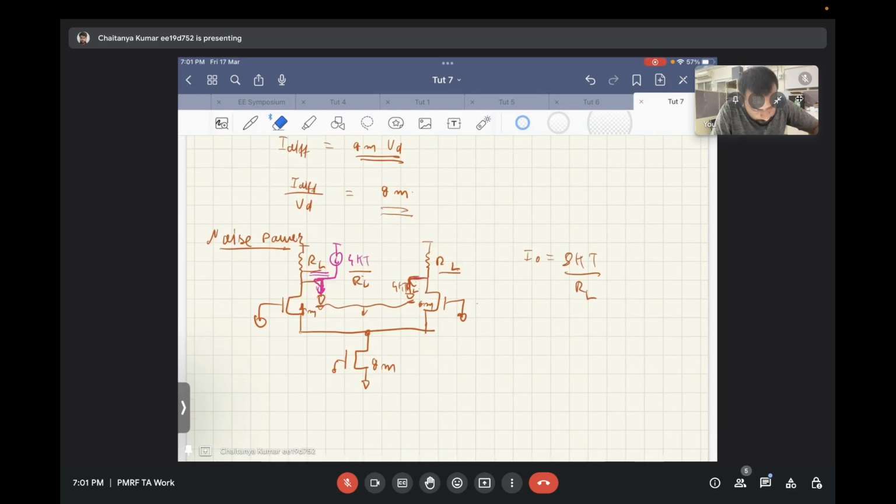Sir, sorry for interrupting, you're telling me about unbalanced output, right, sir? That's not the reason. The noise is uncorrelated because the noise is coming from two different sources, two different random processes, so they will be uncorrelated to each other. Not because of unbalance. It has nothing to do with unbalance. There is no unbalance in this.